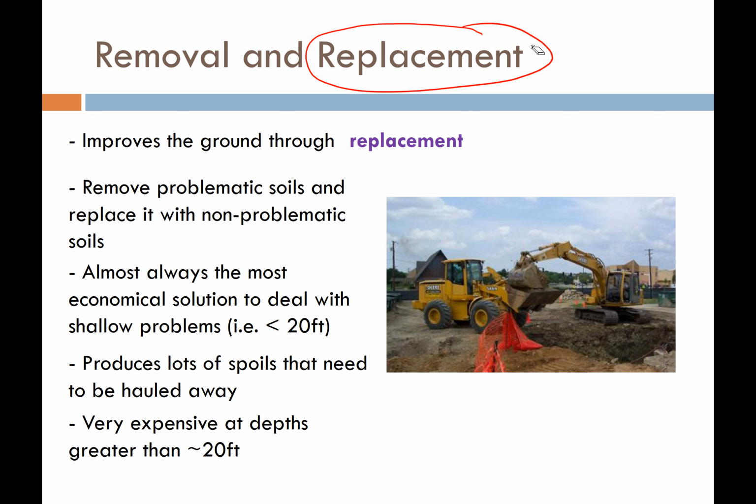You have to put material down there that is self-compacting or that's very, very angular, and so slag is a great thing. Like that's a byproduct of mining. Very angular and coarse gravel that's going to get down, and when it tries to shear, it's going to lock itself up, and so you're not going to get liquefaction. That's the kind of stuff we're going to want to use when we replace our material, especially if we're below the groundwater table.